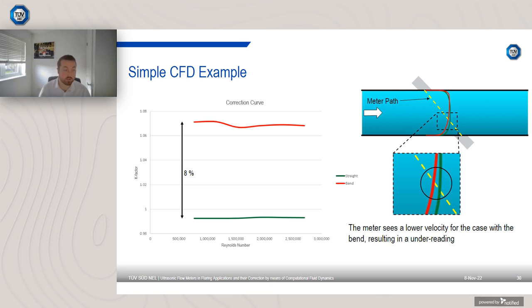And this is actually a good example of when an operator believes that their flow meter is overreading, or that the flow meter is not disturbed by flow disturbances. When an operator believes that they are overreading, but they're actually operating at their minimum purge, then they are leaving themselves open to fines and sanctions.